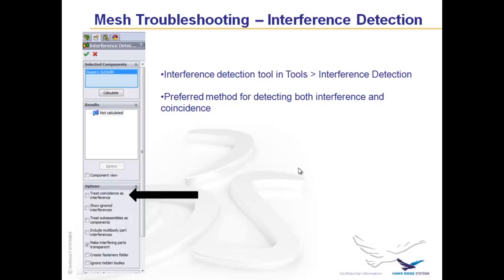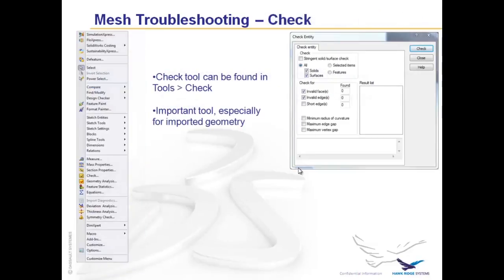What I often find, not with mesh failures, but with solver failures, is that you might think two faces are touching, and you might see them touching, but really maybe they're offset by 1/1000th of an inch and you won't notice it. Even if it's off by 1/1000th of an inch, because it's not touching, you're not going to get the contact set and something's going to fail, probably in the solver. But this is a great way of checking that.